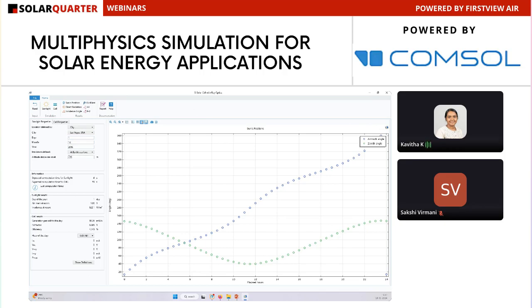You can specify the altitude above sea level. So you can have different input parameter sections. One section here for sunlight properties and another section for cell properties. So you can specify how your solar cell is going to be oriented, the azimuth angle and the cell tilt angle.